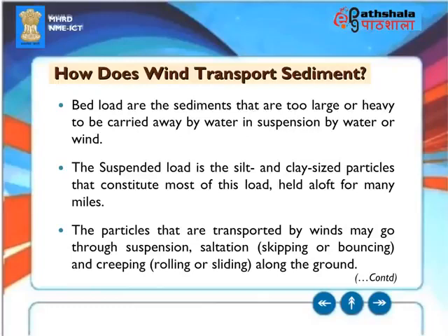How does wind transport sediment? Bedload are the sediments that are too large or heavy to be carried away in suspension by water or wind. The suspended load is the silt and clay-sized particles that constitute most of this load, held aloft for many miles. The particles that are transported by winds may go through suspension, saltation, skipping or bouncing, and creeping, rolling or sliding along the ground.